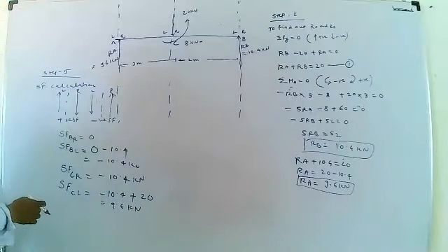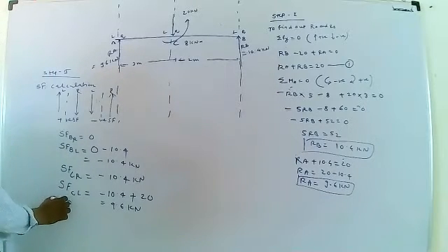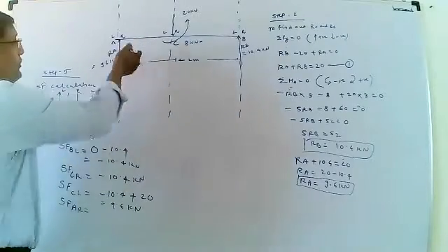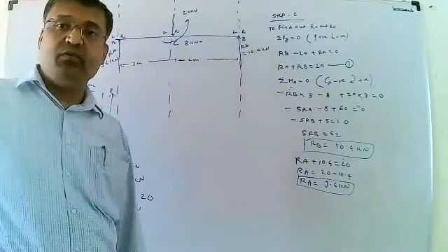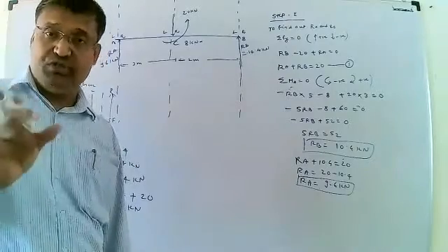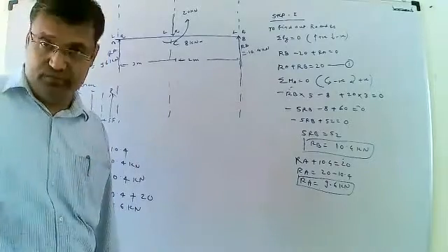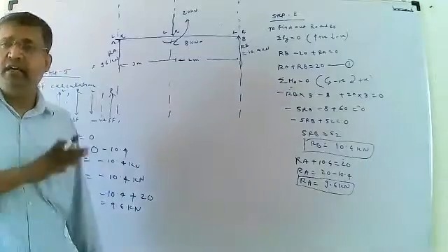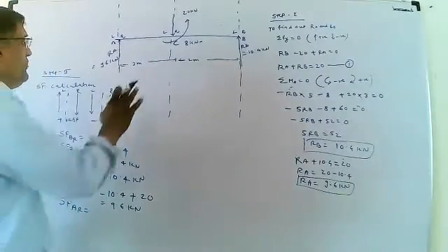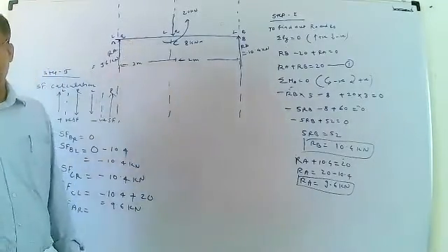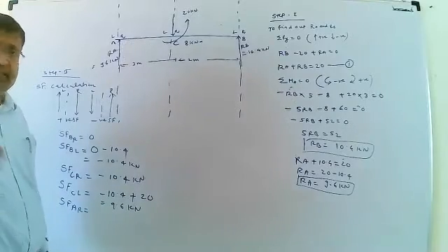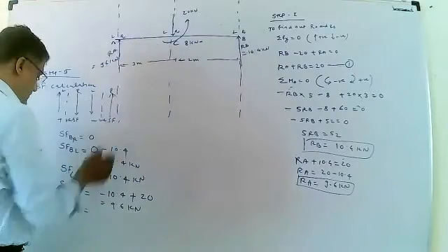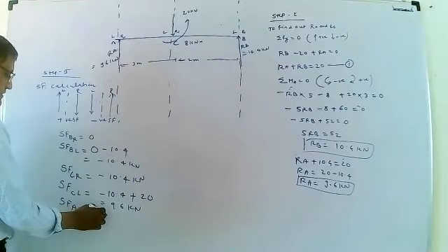Okay. Then here shear force at the point A, right side, this value will be continued at the right side of the point A, because in the portion AC there will be no load. Okay, any type of load, there will be no load in between the portion AC, and that's why this value will be continued at the right side.